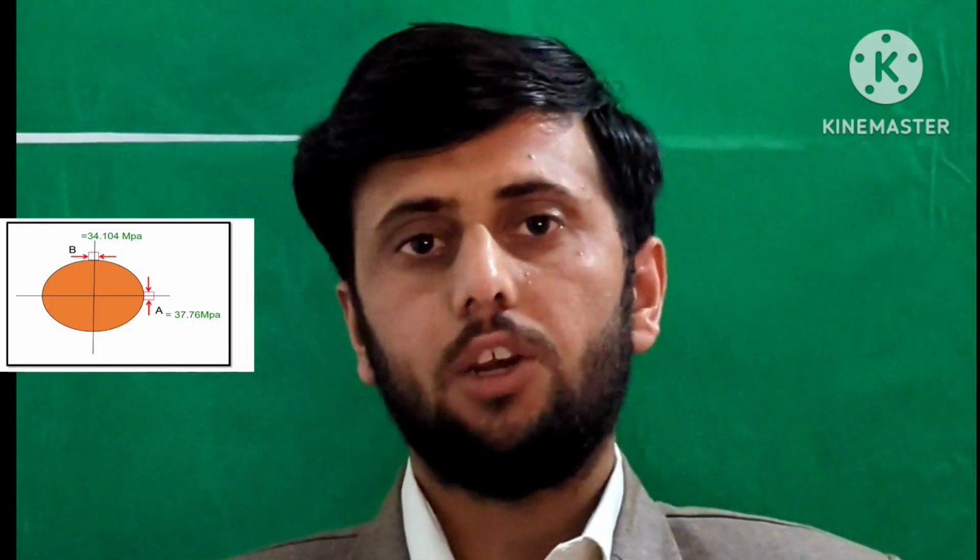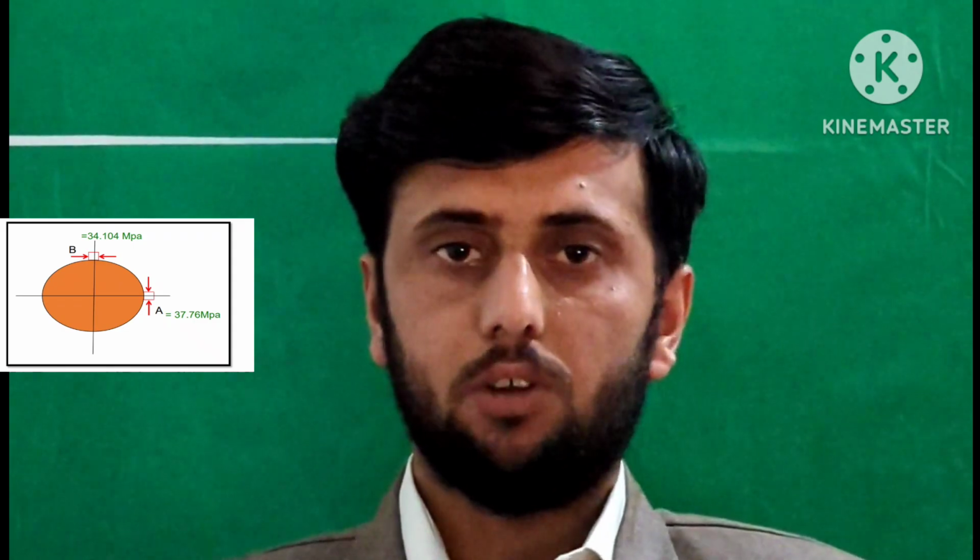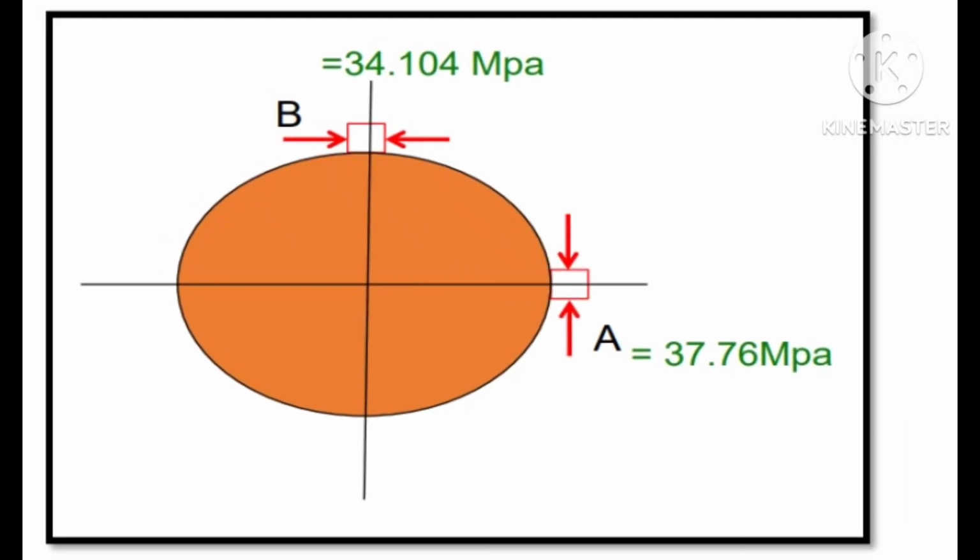After knowing the geology of our area, some calculations are done. After doing some calculations, we decided on our adit opening as a horizontal ellipse to find the horizontal and vertical stresses on our opening. After seeing the depth of the deposit, we make a preliminary design in our mind and sketch it. Our deposit is about 800 meters deep from the surface and spread over 1000 square kilometers.